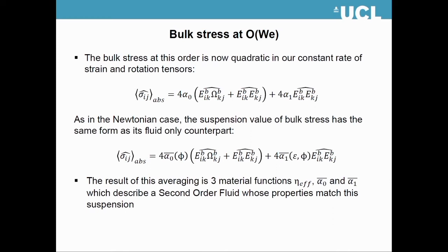each term. So what we do is say, okay, these are the effective terms, much like we did with the effective viscosity. They will analytically depend on B, the radius of the sphere of influence, but using our matching to Krieger-Dougherty, we can substitute out that B for a dependence on the concentration. And so everything now depends on this concentration and this ratio of material parameters, epsilon.